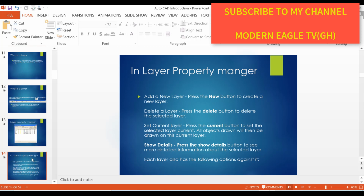In Layer Properties Manager, add a new layer: press the New button to create a new layer. Delete a layer: press the Delete button to delete the selected layer. Set current layer: press the Current button. All objects drawn will then be drawn on this current layer. Show details: press the Show Details button to see more detailed information about the selected layer.